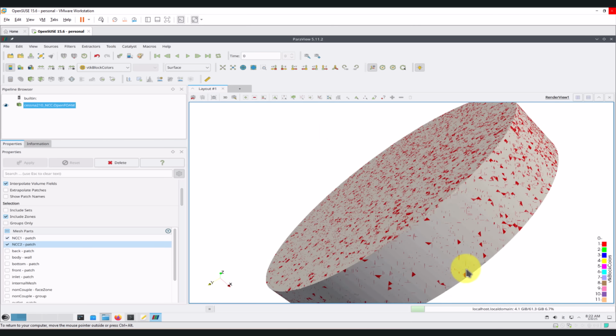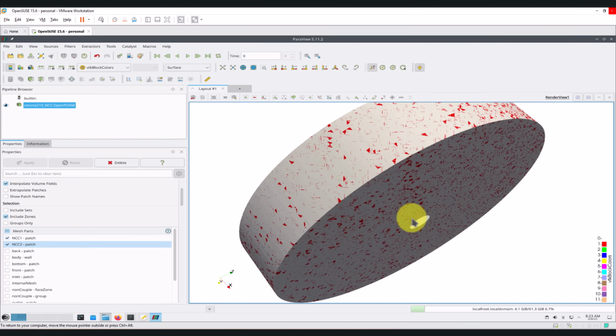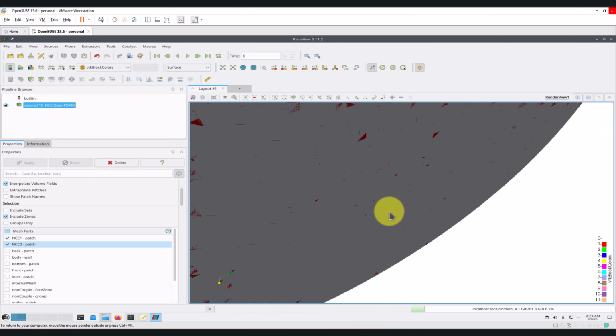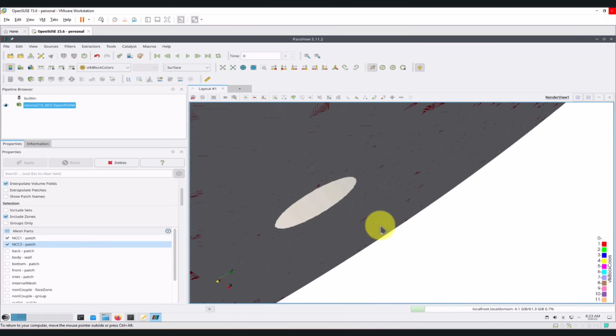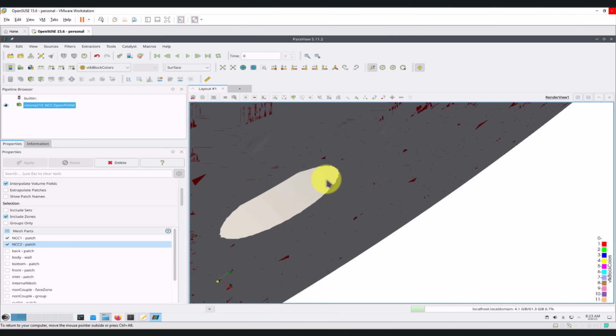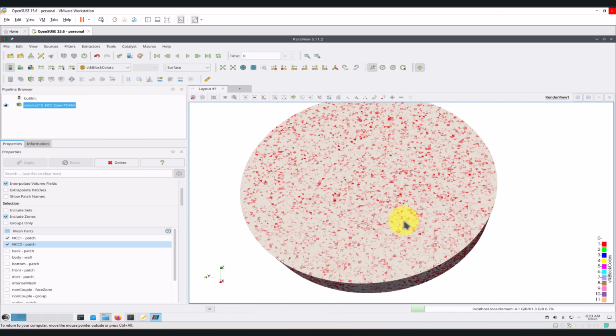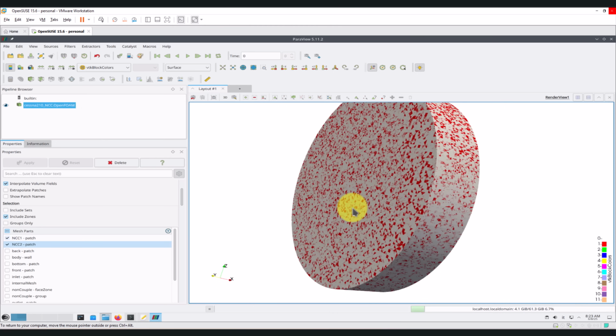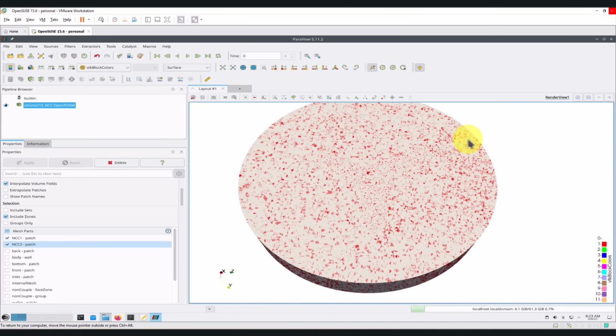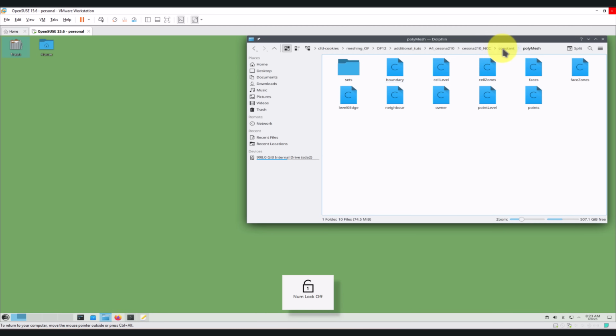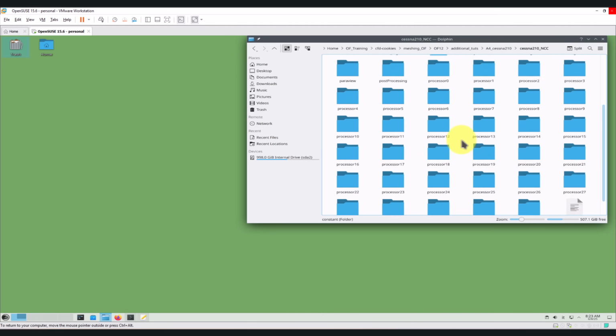Also, if I recall, this is a coarse mesh. There are some issues here. See that you have those small regions, and that can have an influence on the quality of the interpolation. As you run the fine mesh, if I recall, the interpolation is much better. And actually, let me go here.